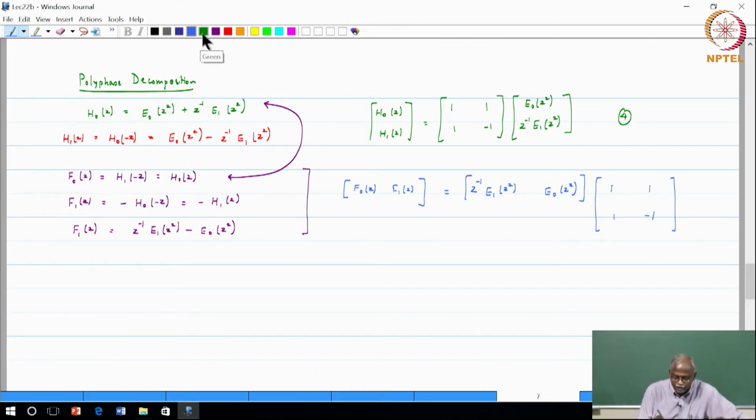Now, the reason for doing this also highlights one point that we had mentioned earlier. We said that, remember that this is type 1 polyphase decomposition, type 1. What was the type 2 polyphase decomposition? What would it have been? It would have been z inverse R naught of z squared plus R1 of z squared, right. The delays are in a different order as in the type 1.